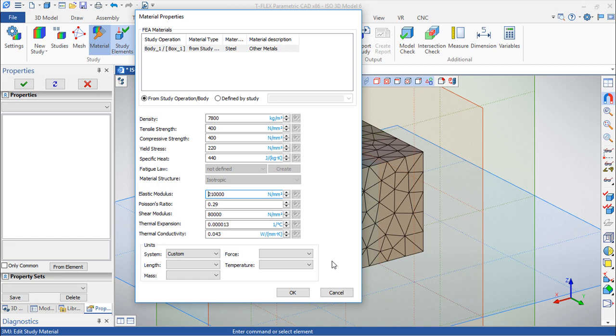So it will pass to an area that will no longer recover the shape, and it will start to stretch with almost zero force, okay? And this phenomenon is called the plastic flow. And if you see on the diagram, it is basically a more or less horizontal line, because it means that with a very low force or load, it will start to elongate.